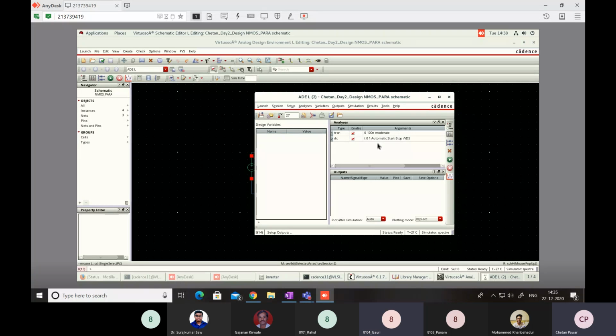I have shown you before the lunch time there is an input.scs file. That is a netlist file. So this EDA tool collects all these things like transient analysis, DC analysis, in the proper format, and it creates one netlist file. And that will be applied to the simulator.